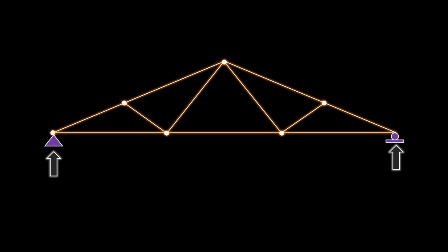From a practical perspective, we do not want to transfer the outward thrust forces to the wall because the wood-framed wall does not have the capacity to support lateral out-of-plane loads acting at the top of the wall. As we have said, to prevent the development of lateral reactions in our analysis, we will replace one of the pinned supports with a roller support that is free to move laterally. Such a system does not have lateral reactions. A truss designed under these boundary conditions will have maximum member axial forces, and this is what we want.